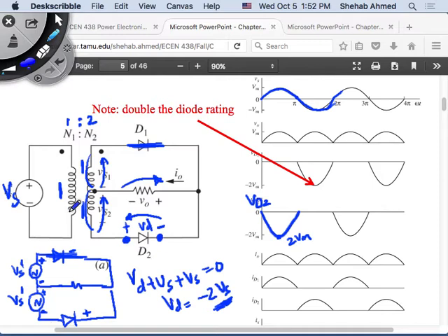And so you get the peak is half the size. The peak is half? No. If this is 1 to 1, then the output voltage on the resistor is equal to the input voltage supplied as well. So my output voltage is equal to my input voltage in the positive half cycle, exactly equal, because I chose 1 to 1 to 1. But I can choose 1 to half to half. In that case, yes, what you're saying is right. The output voltage would be half the value of the peak.